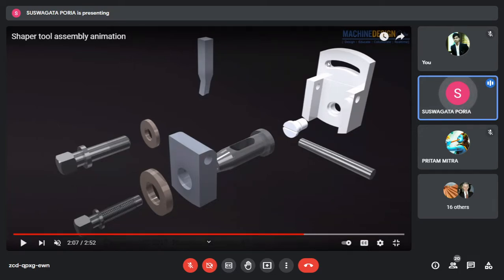Now you can see in the swivel plate there is a slot. Why is there a slot? Slot means that we can put the screw anywhere in the slot. That's why the slot is there. If it were always fixed in its position, then there should be a hole, not a slot. A slot means that we can fix the swivel plate anywhere around the slot.